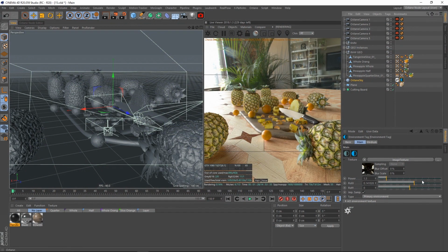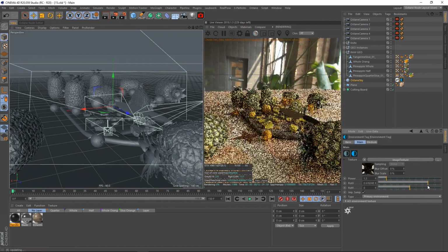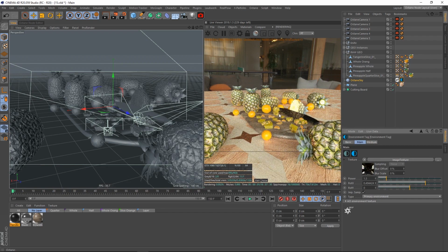I think you'll agree that it looks better this way than if I rotate the HDRI and just have it front right behind, just shining on like this. This just looks horrible, right? The scene was not set up for that. And you'll notice our materials don't look very good either. So I set my lighting up first, and then I got everything to texture and work correctly from there.